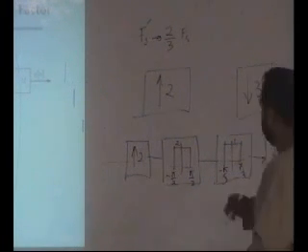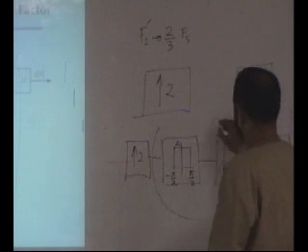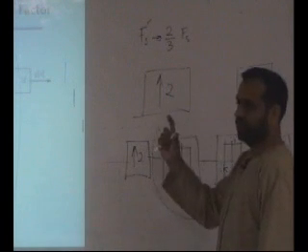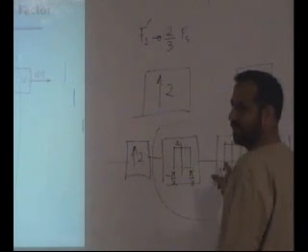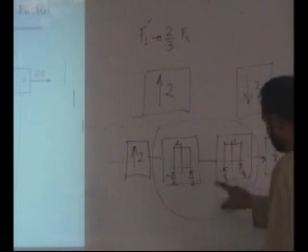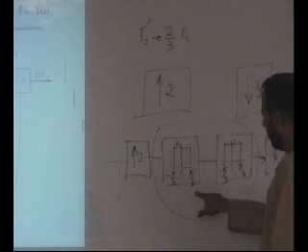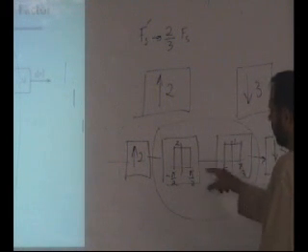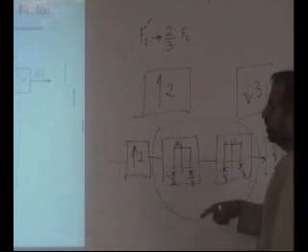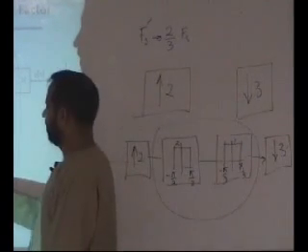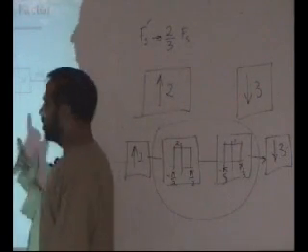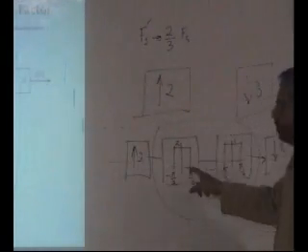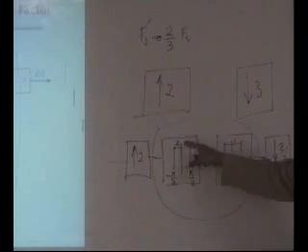But remember that these two filters can be put in as just one filter, because they are low pass. So find out the maximum of these two, pi by 2 and pi by 3. The maximum of this will be the minimum of pi over this. So you find the maximum of L over M, so pi over K. In this case you put a pi by 3 filter with gain 2.